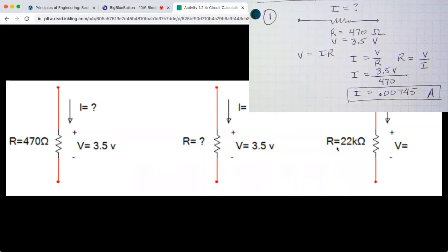And then also, you notice there's a K on this one. You probably know K without me telling you. Kilo, that's right. Kilo ohm, so that would be 22,000 ohms in that case. And then notice this one's got a little M. You remember what a little M is in the metric system, which is, that's right, it's a milli. So you divide that by 1,000. You multiply kilo by 1,000. You divide milli by 1,000. And you divide micro by 1,000,000.